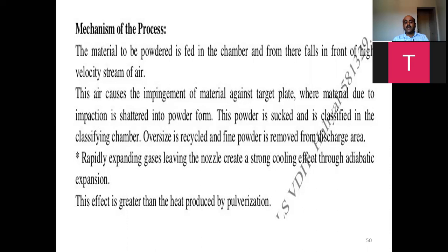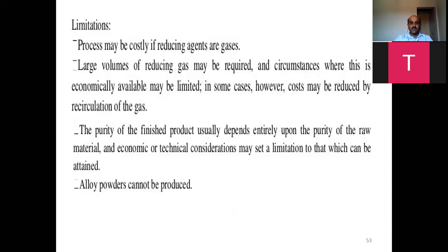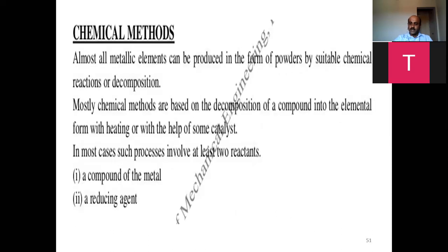Rapidly expanding gases leaving the nozzle create a strong cooling effect due to adiabatic expansion. This effect is greater than the heat produced by pulverization. So these are the techniques I wanted to discuss in today's class. Other techniques are there, the chemical methods and so on. I will come back to these in the next classes next week.